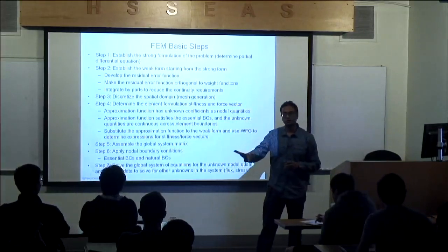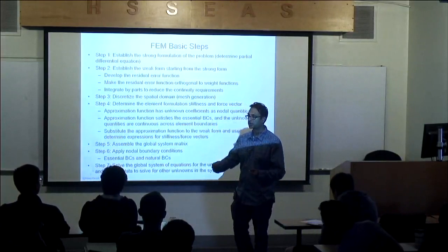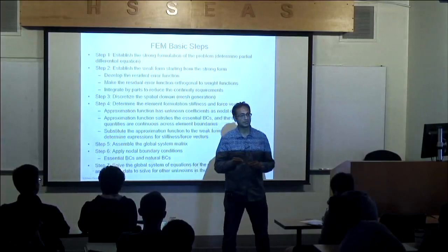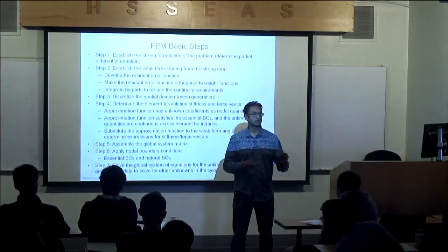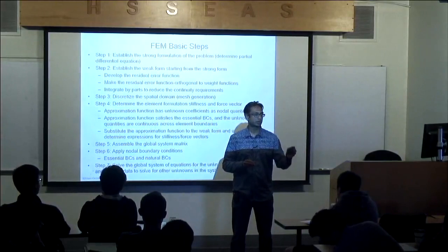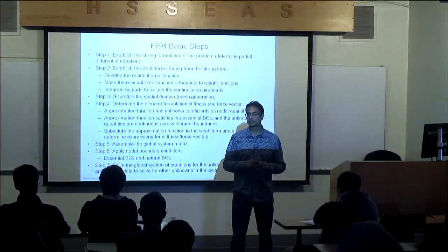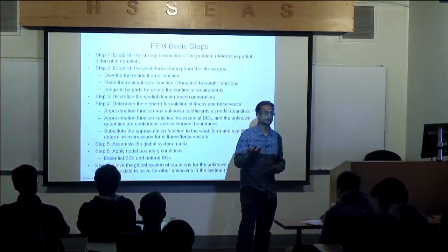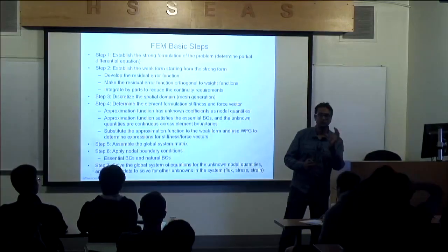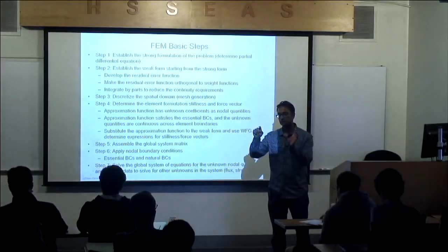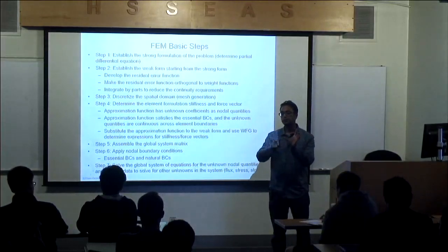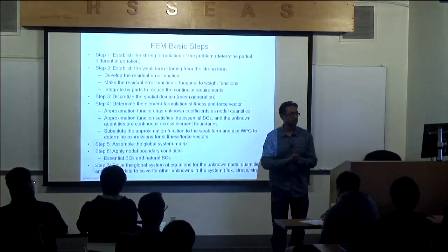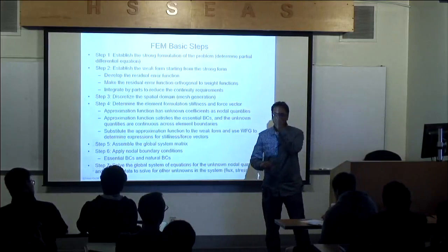And then once we get to the weak form, we go to the weak form Galerkin, the approximation method, and then we apply the approximation method by selecting the approximation function so it's sufficiently differentiable so that it is continuous, so that it satisfies the essential boundary conditions of the problem. And then we'll select the weight functions to be the shape functions and make the error orthogonal to each of the shape functions or the basis functions. In weak form Galerkin, there are the phis. In finite elements, there are the shape functions N. Excellent. And then from there, I have formulated the element formulation.